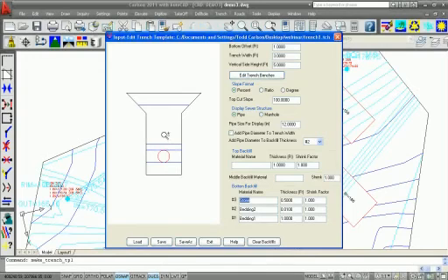Okay? And then, so what's really fluctuating is that these amounts are locked at the top, at the bottom. The stone is fixed. The middle bedding, bedding 2, is going to fluctuate as the pipe gets bigger or smaller. And then this middle here will fluctuate depending on how deep the trench is. So that's going to be our middle, or oops, this was gravel. That's going to be our middle backfill quantity, and we'll just call it fill.